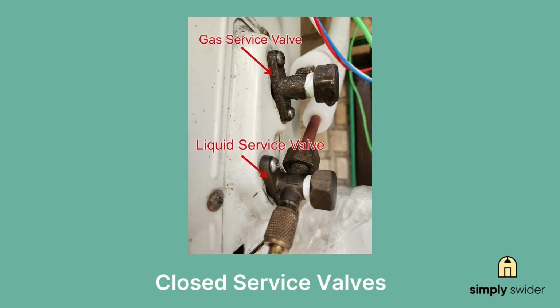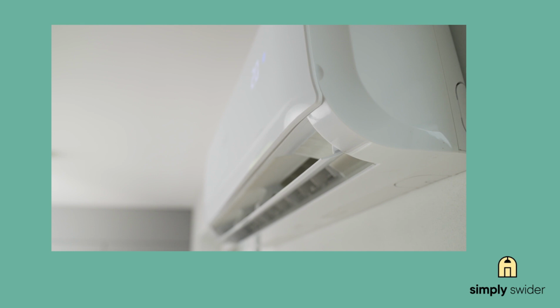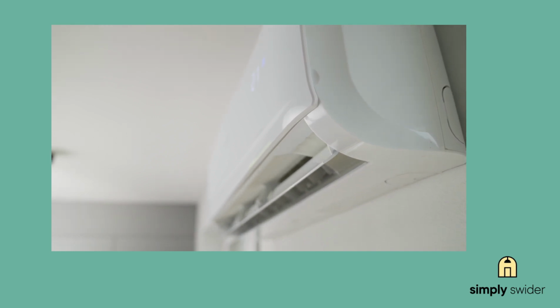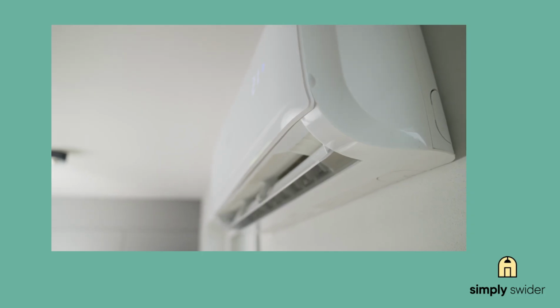This one's mainly for new installations, but it happens more than you'd think. The liquid or gas service valves on the outdoor unit get left closed after installation. Pure installer oversight. I've seen seasoned techs do this. They're focused on leak checking and just forget to open the valves. Here's the dead giveaway. The error shows up almost immediately on the very first startup. If your system worked fine yesterday and suddenly shows C422, this isn't your problem.